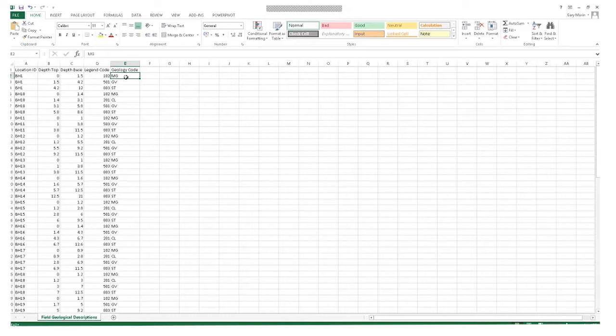If you want to visualize it differently because you're not too sure how to classify the geology, just put your geology codes in there, however what feels best for you. The important thing is for each boring location, we have this nice consecutive row of numbers going down on it, and they don't overlap or anything like that because it won't look right when you bring it in.